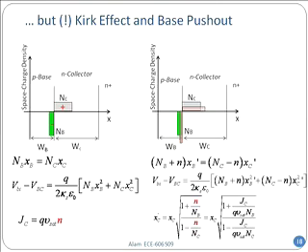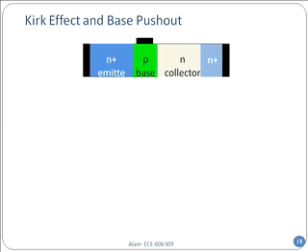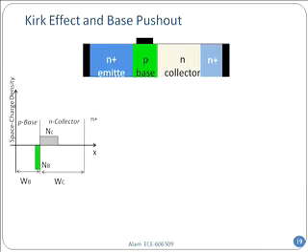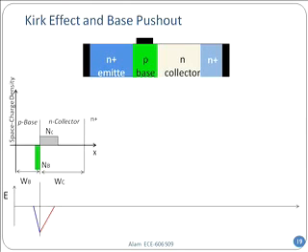What was the value? About 10 kilovolts per centimeter, right? Do you remember? So here when you apply a volt or a 2 volt on the collector and you have this tiny depletion region, the field is really much higher. So in that case, your current will be simply Q Vsat multiplied by N. So you can relate the carrier concentration N to the collector current Jc. And you can put it in here. That's exactly what I have done. Now comes the punchline. Oh, sorry, I have another slide on here.